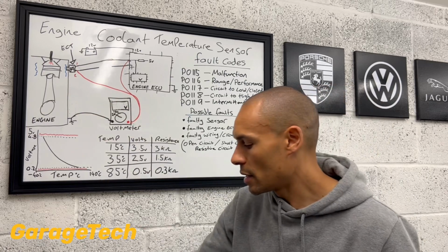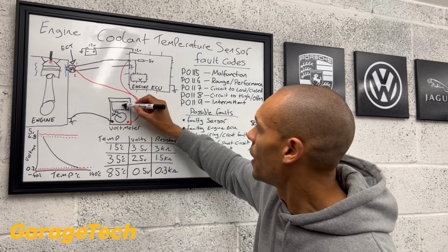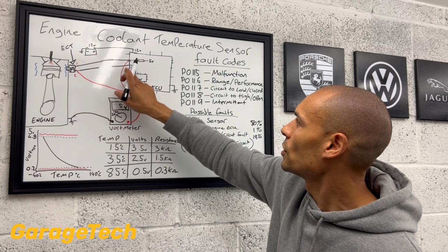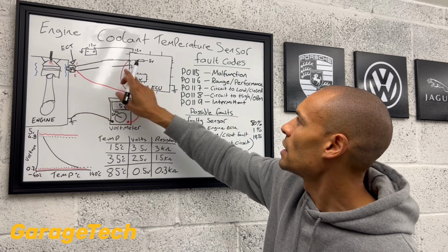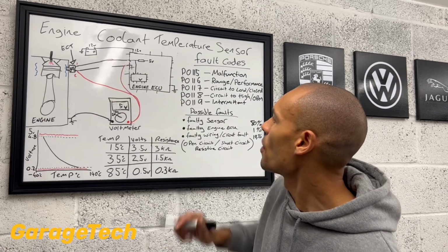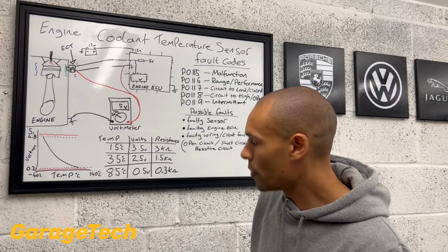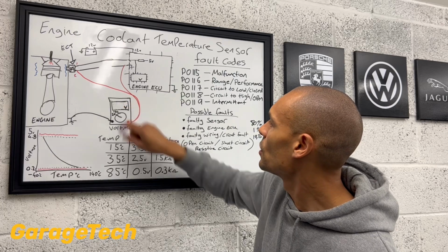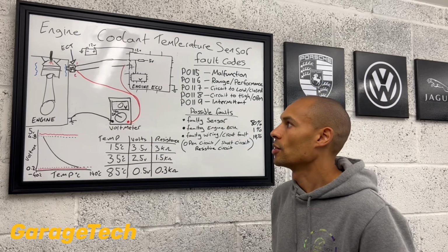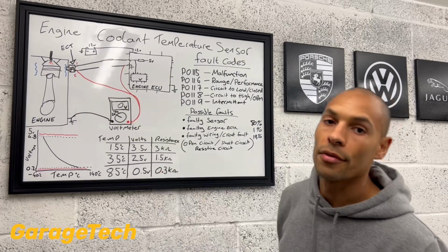That's going to give you an indication then that you've got an open circuit on that wire that's going back to the engine ECU. So if you go back to the engine ECU and check there, for example, with your multimeter set up as it is, you should then read 0 volts. And that's just going to confirm that you've got an open circuit then on the earth.